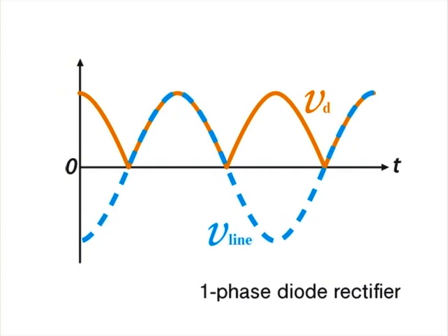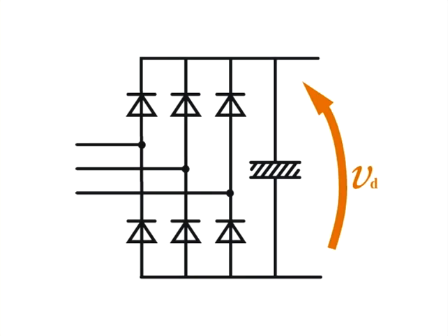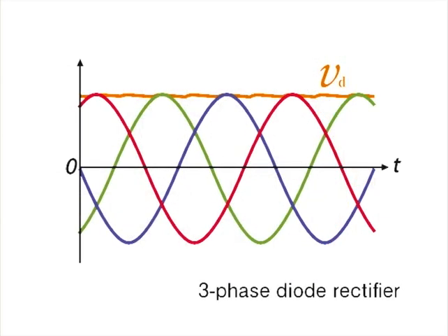rectification circuit's output voltage. Shown here is a three-phase AC voltage rectifier. A very simple process using an electrolytic capacitor to remove the ripple from output DC voltage makes this a popular choice. One drawback, however, is that input current is rendered as distorted waveform and not the preferred sinusoidal waveform. Not only is the power factor decreased, but because higher harmonic waves are generated when the input current is distorted, other electrical equipment may be adversely affected.